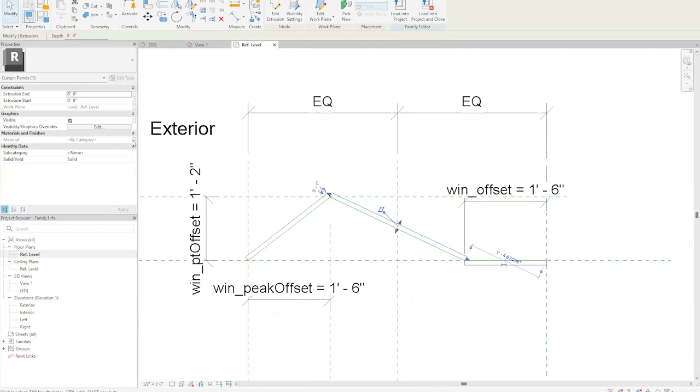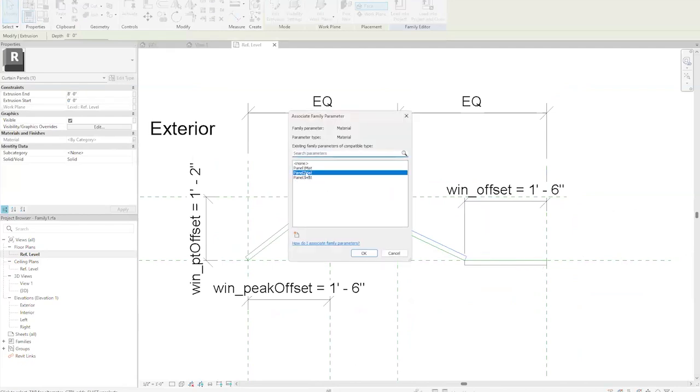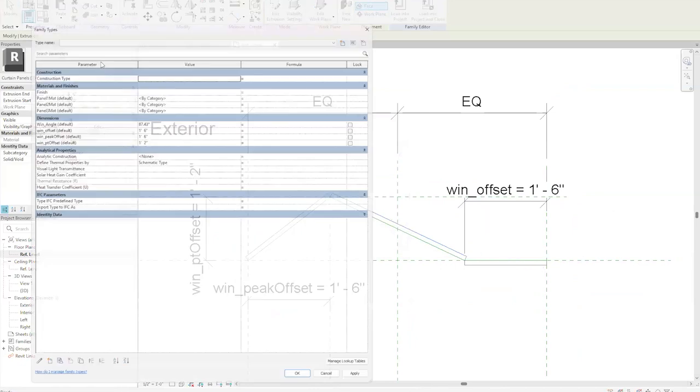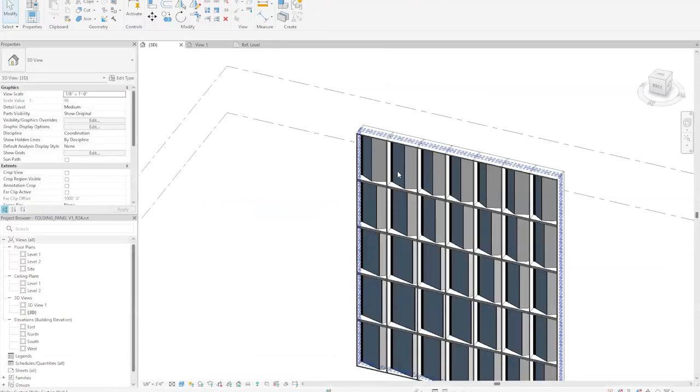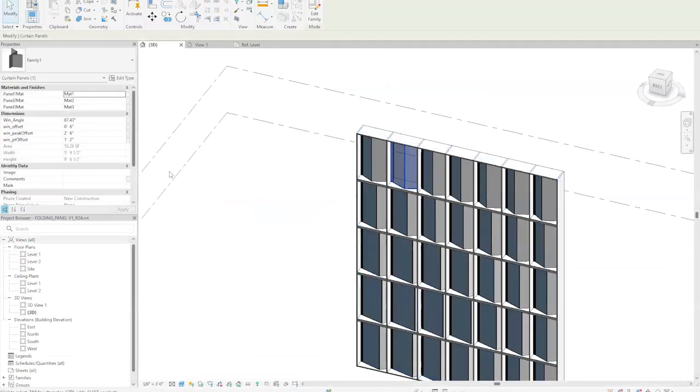On this geometry, we're associating the material with a parameter, because that's where you really get powerful: being able to create a proper family in Revit and then manipulate it with a data-driven workflow, either in Dynamo or Grasshopper. So there are type or instance parameters driving what we're modifying, and I think they're instance-based materials as well. So that's what's going on.